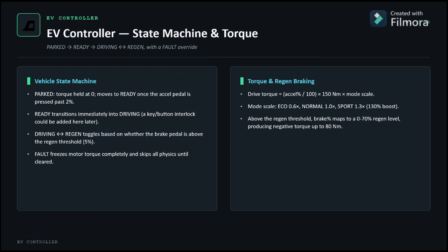Parked means torque is held at 0. It moves to ready once the accelerator pedal is pressed past 2%, and ready transitions immediately into driving.